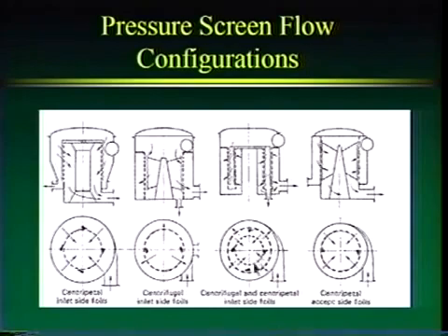This one I already mentioned to you. Because the pulp is flowing through two baskets, there's higher screening face area, so there's more throughput. And then in this one, because the foils are on the inside, the foils don't have a chance to break the contaminants on the feed side, so it's a little bit gentler. And also, if we have heavyweight, high-density contaminants, they're not even going to see the face of the plate. So you can have pressure screens in several different configurations.